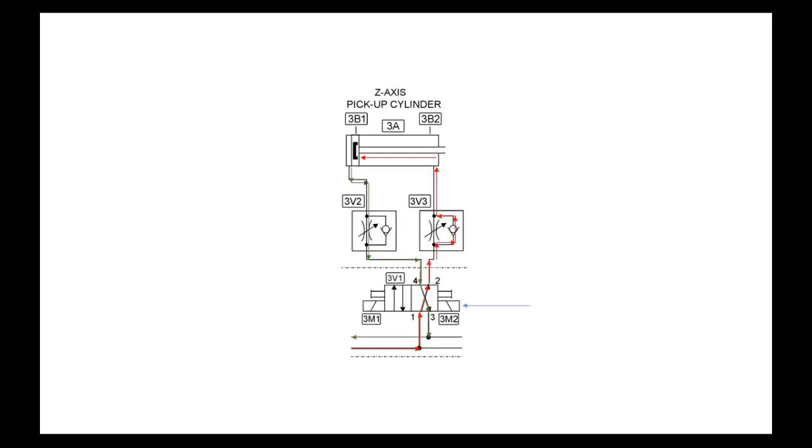So what we do when we meter out, we control the exhaust. And like I said, in hydraulics, if you're going to do the same speed in both directions, you won't have a check valve. It'll just be a flow control valve. Because no matter which way it's going, we don't call it exhaust, it's tank, on your tank side it will have the same pressure as your other side.